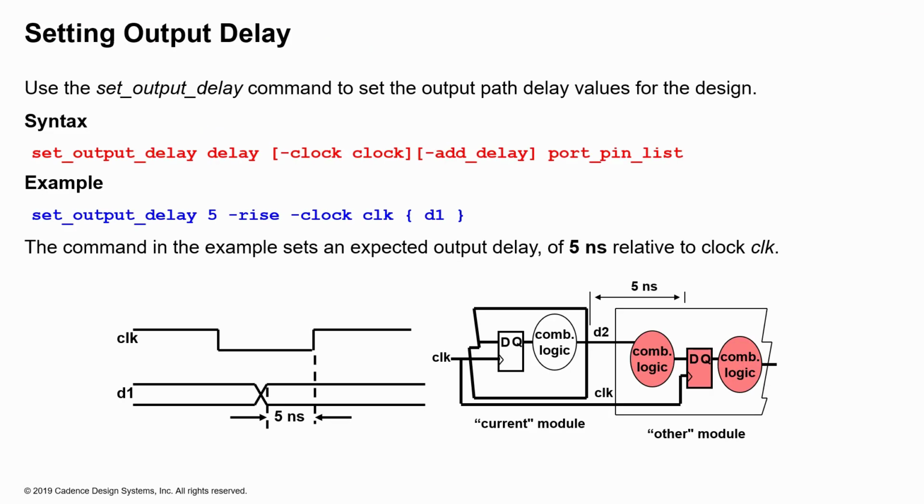Ensure that you set the output delay using the set_output_delay command for all the output ports in your design. This ensures that all the register-to-output paths meet the timing specified, and therefore the tool uses this value to constrain the output ports.